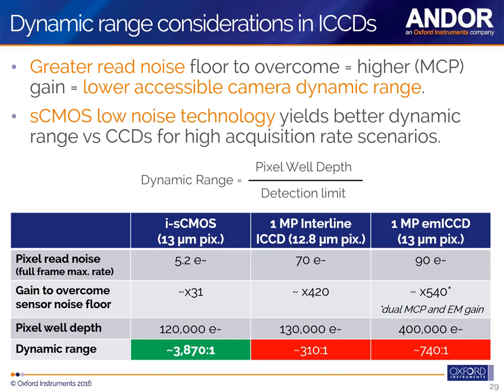So let's do some maths here, not too complicated. To really access a good signal to noise ratio, you can say as a rule of thumb that you need to apply 6 times the value of the read noise in terms of gain.